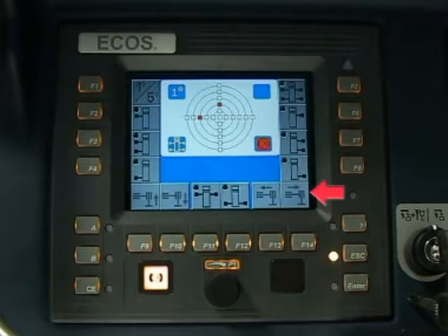When a preselection is made, the outrigger beam and cylinder symbols will change from grey to black to indicate the permissible functions. All preselection buttons have an indicator light to show the selection is active. The preselection is green when active and remains active for approximately 10 seconds to allow a function to be selected.